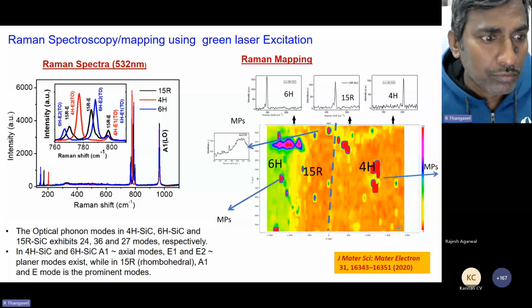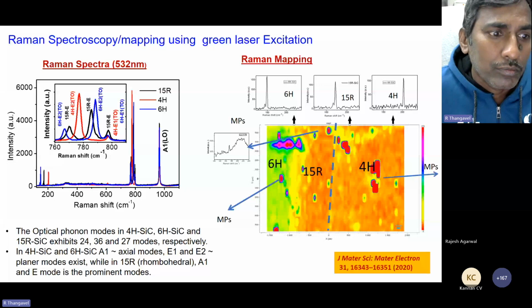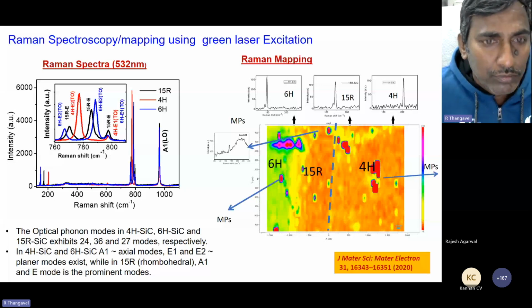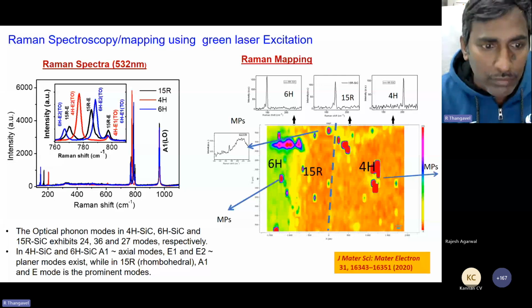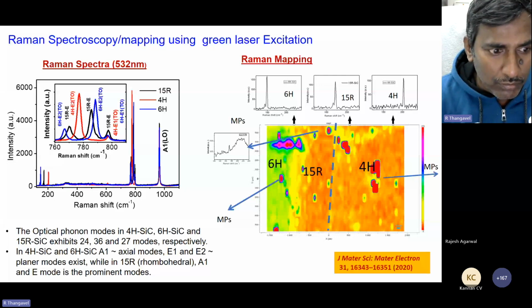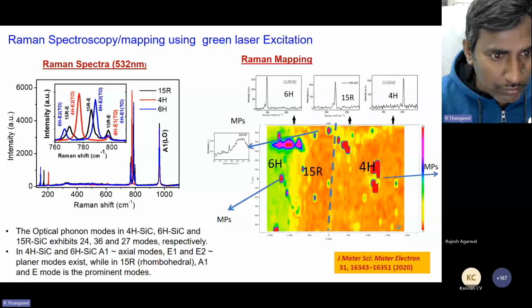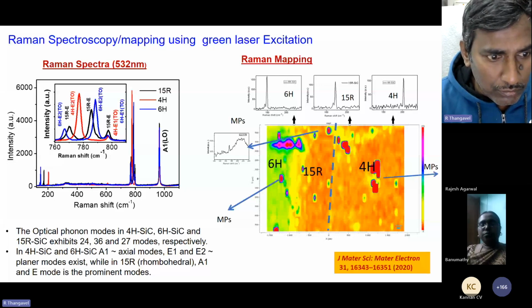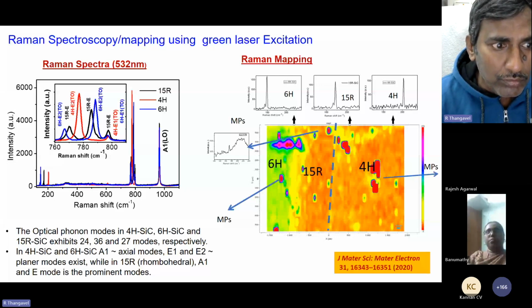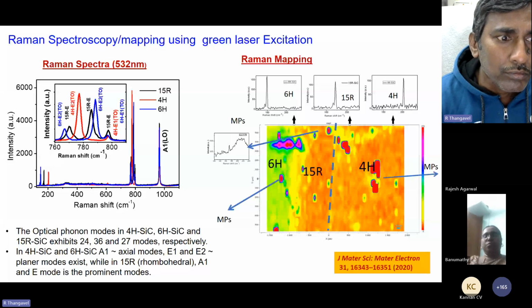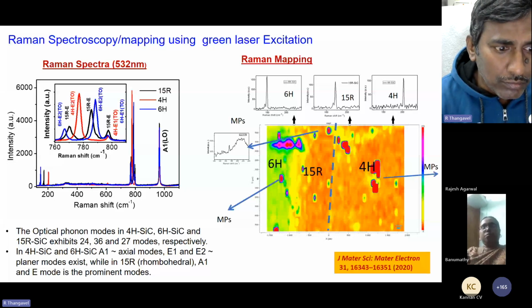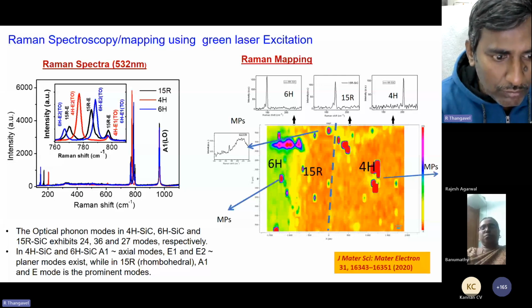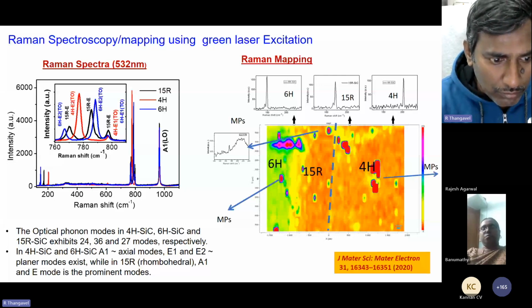Then metallization and dielectric coating. For metallization, one can use thermal evaporation, and for dielectric coating, one can use sputtering or CVD. These are several techniques by which dielectric coating can be done. Now, photolithography: there should be a mask aligner and spin coating, with spinners. Mask fabrication, a laser writer will also be there, and etching, either wet chemical etching or dry etching. Dry etching is basically reactive ion etching or DRIE.